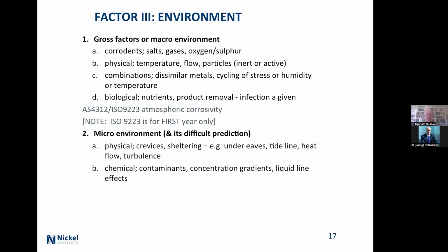Heat flow, well, the heat goes through, and on the other side, the side that it comes out into, say, water, then you can get fouling on the surface. And often fouling is basically going to be the place at which the corrosion will occur. And turbulence, and I don't just mean turbulence as in rough flow or bubbling and so on. I mean, you're going down a pipe and you hit a weld and you get turbulence where you roughly double the velocity on the downstream side. Or you go around a sharp curve rather than a swept curve and your velocity is high.